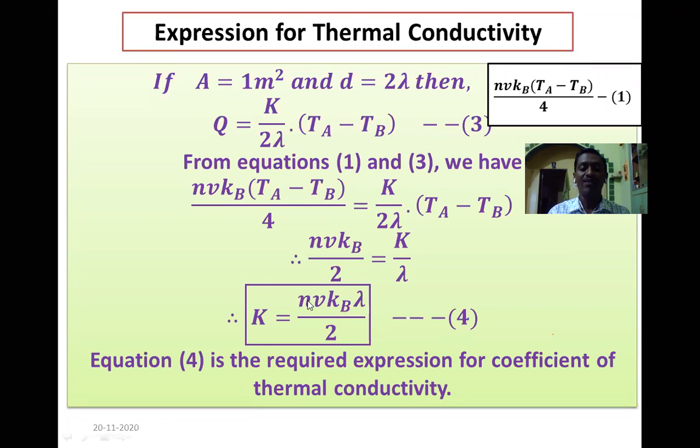Again, it depends upon the average thermal speed, or mean velocity of each electron, upon the Boltzmann constant, and the mean free path length. If the mean free path length is more, it has more ability to transfer the heat, because during a mean free path the electron travels with very high velocity. Therefore, if collisions are less, the mean free path length will be more, and then the thermal conductivity will again be more.